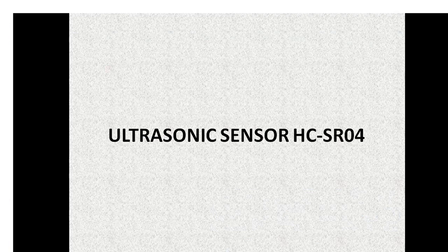Now my second sensor is the ultrasonic sensor HC-SR04. HC-SR04 is an ultrasonic ranging module. It provides 2 cm to 400 cm non-contact measurement function. Its ranging accuracy can reach 3 mm and its effectual angle is 15 degrees. It can be powered from a 5 volt power supply.